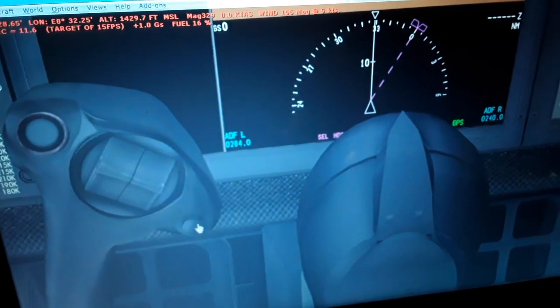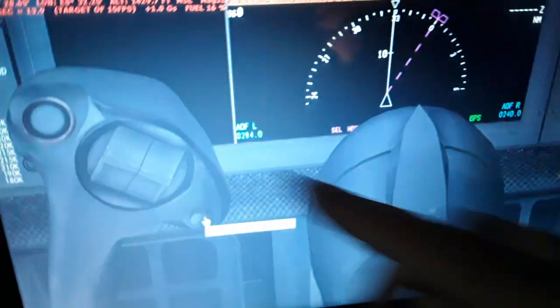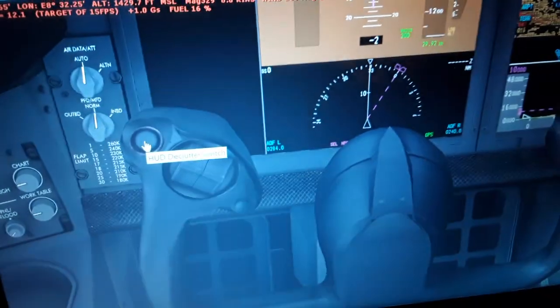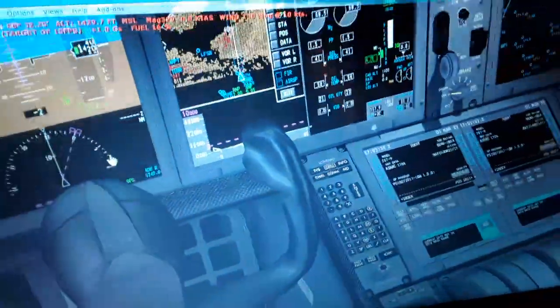We have the autopilot disconnect switch and the head up declutter switch, the flaps limits over here. So we use the horizontal trim stabilizer. This is a fly-by-wire aircraft. As I told you, it has also its flight control computers to trim the aircraft automatically when we fly without doing any input in this switch for the horizontal stabilizer or the alternate, or the trim wheel.